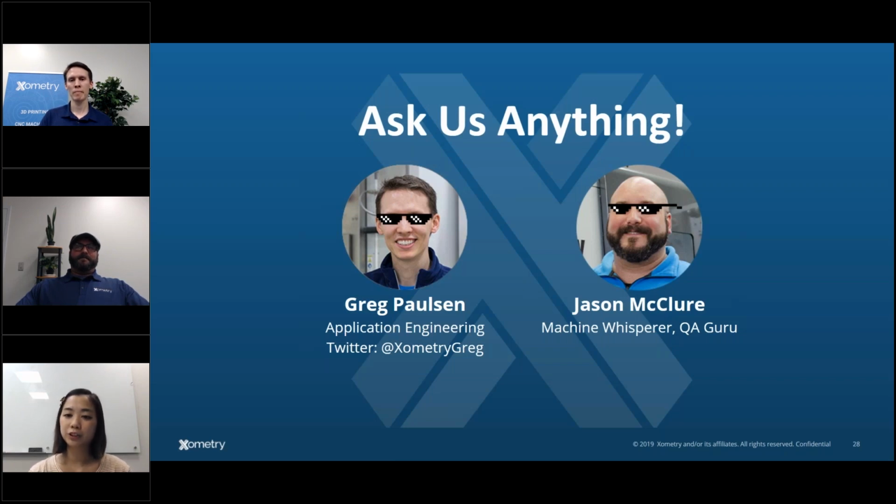Okay. Question from Patrick here. How would you show a dimension like max R 0.005 in a 3D model? So you're talking about the maximum radius of maybe a protruded feature or a hole, I'm guessing. A lot of times that could just be a unilateral distance dimension. If you have a hard stop max, it may be as simple as that plus or minus to talk about that dimension. If I didn't interpret that right, shoot me an email and I'll make sure to interpret that correctly.